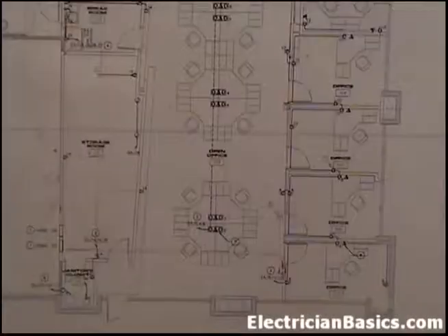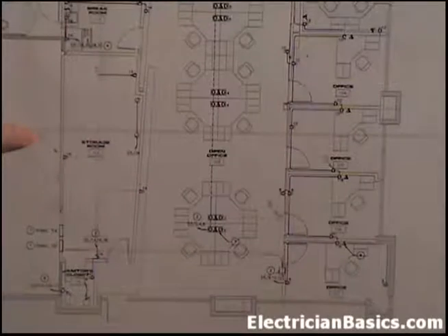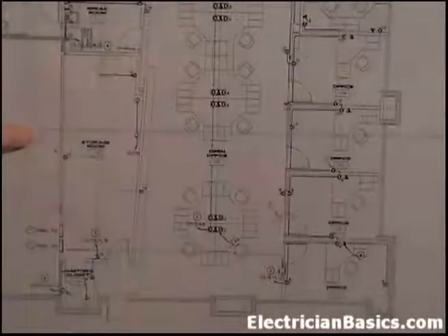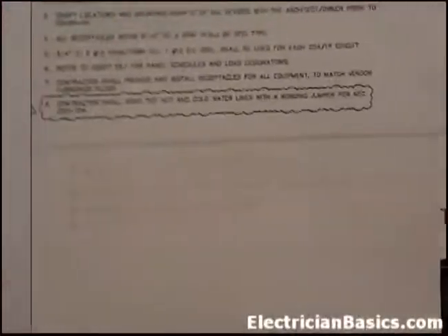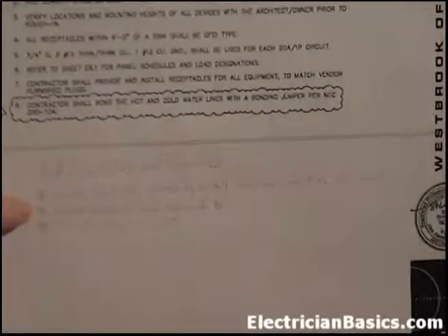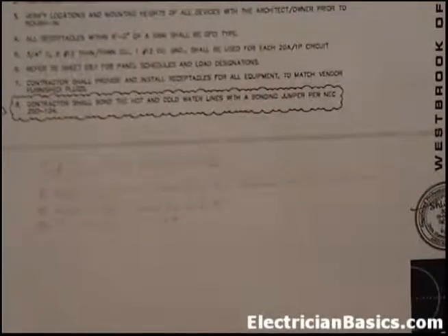Now we had a note 2. Right here was our note 2. So let's take a look at what note 2 says on our red line notes and symbols. So here we are now at red line note number 2. It says unistrut on wall for home run conduits. So that note is pointing out that when they did that, they have unistrut and they have several conduits on that wall, and instead of just overlapping them on the drawing, they're pointing that out. And again, when you go from junction box to panel, that'll be very clear when somebody's actually looking at the diagram.